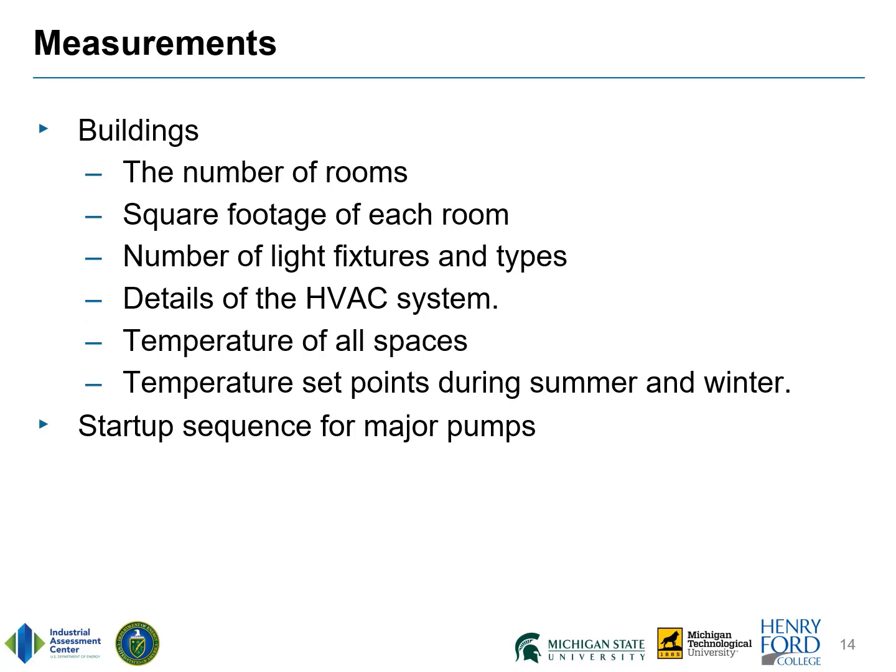For the buildings, be sure to collect the number of rooms, square footage of each room within the building, number of light fixtures and types, and details of the HVAC system. Be sure to record the temperature of all spaces and obtain the temperature set points for the buildings during summer and winter.